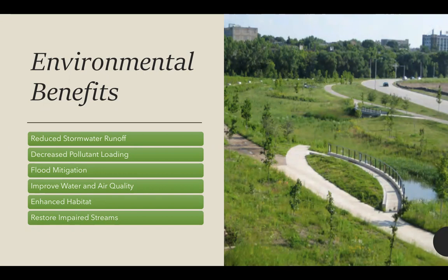They also work as a small-scale wetland within these urbanized areas, so they're able to hold water for a longer time and collect especially water from parking lots or other impermeable surfaces, and the soil and plants help to trap that silt and pollutants collected from the runoff and keep it from getting into the stream channel.